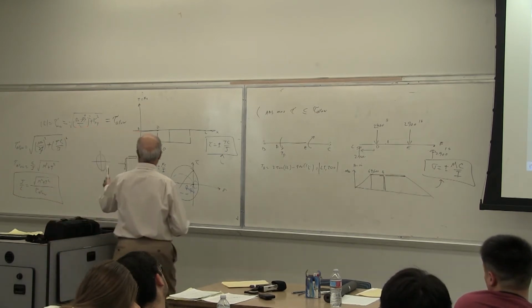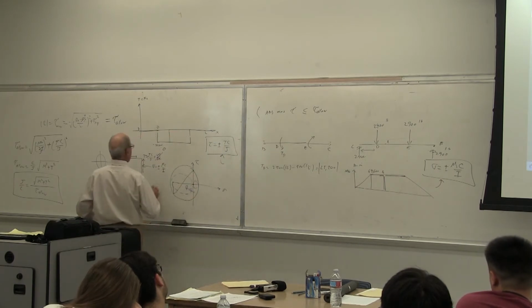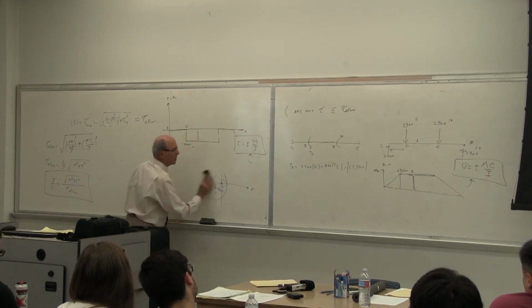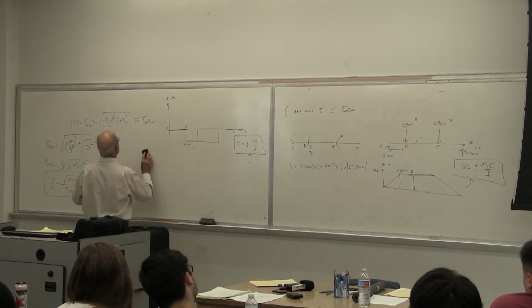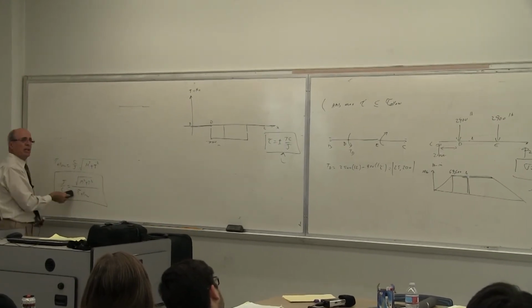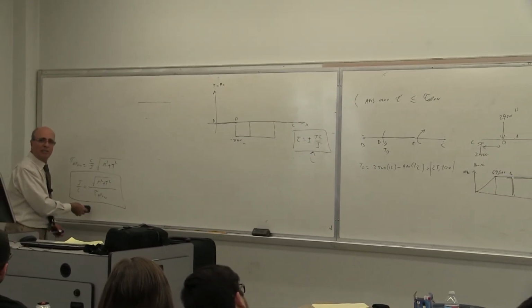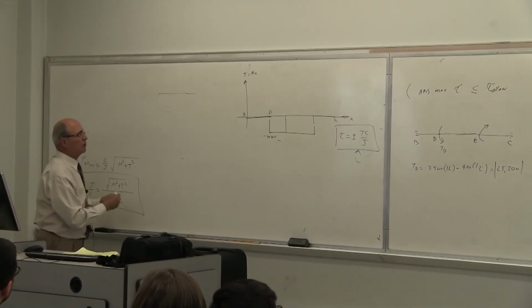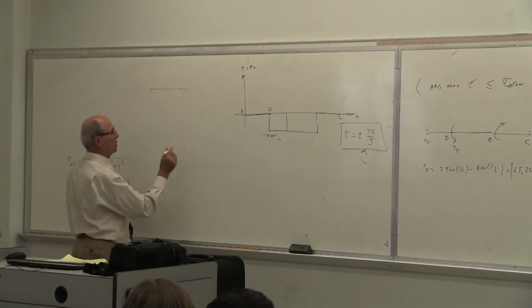Nevertheless, this is the equation. One equation answering that. Now, if I want to find the size of my shaft, what do I do? I don't need to worry about the Mohr circle. I don't need to worry about all of this. The criterion I used to come to this conclusion is maximum shear stress, yes or no? All you have to say is this. This is the answer to this problem.